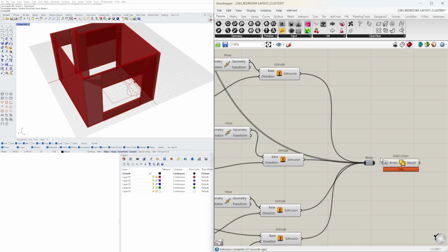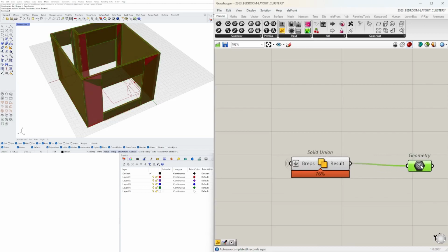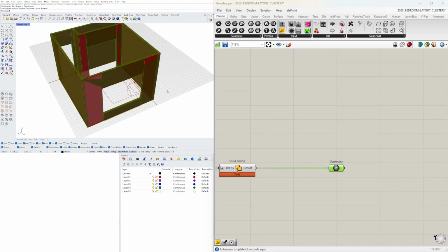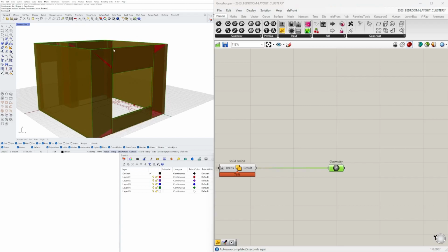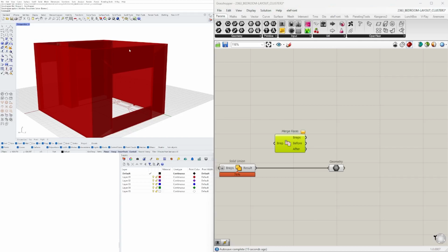Because the relay doesn't have the hidden wires, so I'll actually go like this and then do a geometry component. And notice that we have something here called a crease, which is when you combine solids, you get this. To remove that, you go to merge all faces, which means if this face is joined together and you have a crease and they're coplanar, it gets rid of it. Show you.